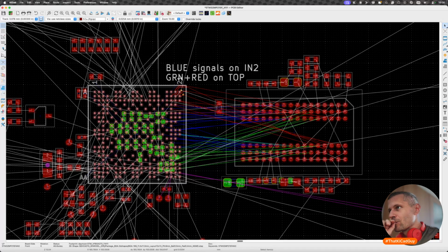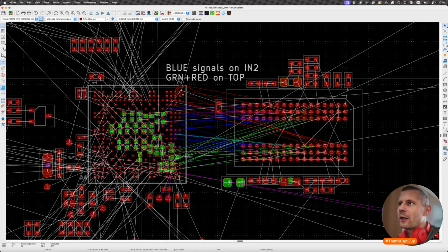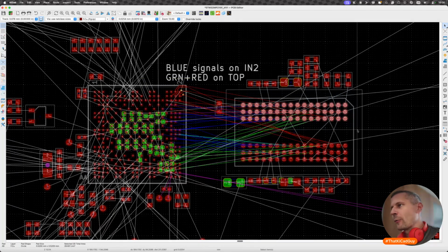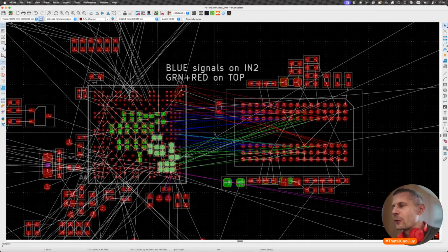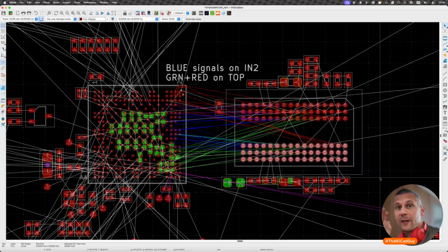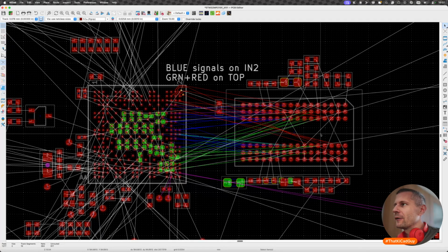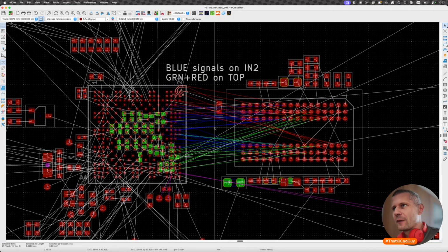Now, 10 minutes ago, or 15, we solved the issue with blue signals, the blue signals that go on the inner layer. We can see that the majority of them from the upper half of the BGA package go to the upper part of the BGA of the memory module, and signals from the bottom go to the bottom part. That's good, that's fine. But now I can see that a good half, maybe even slightly more than half, of the red signals from here...